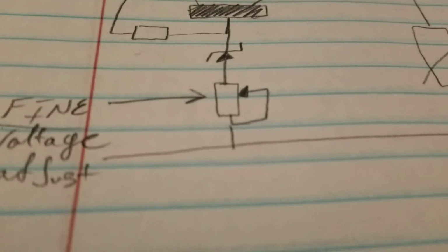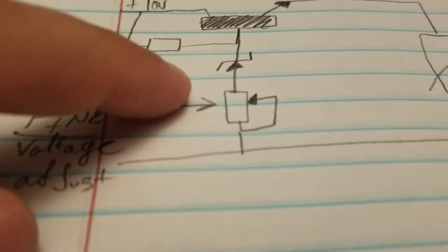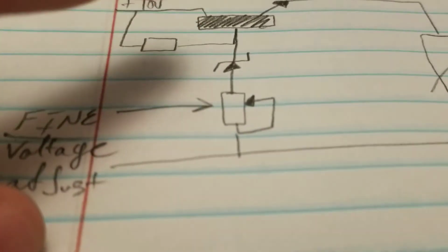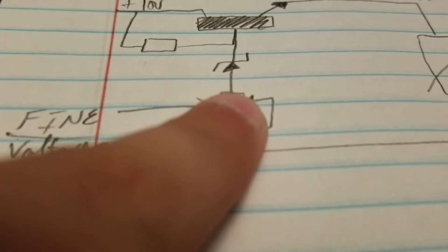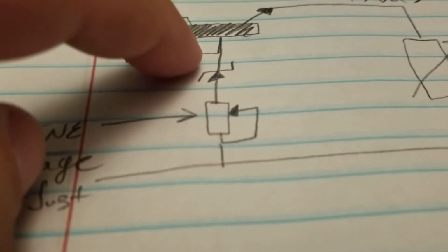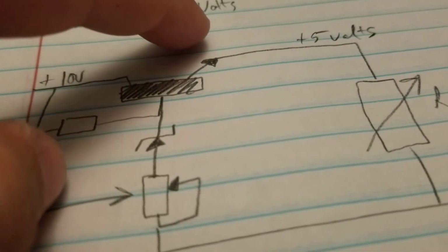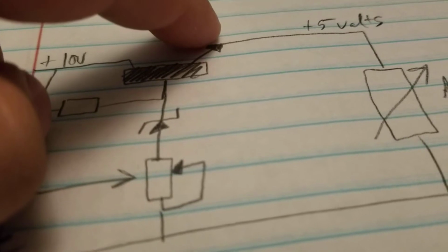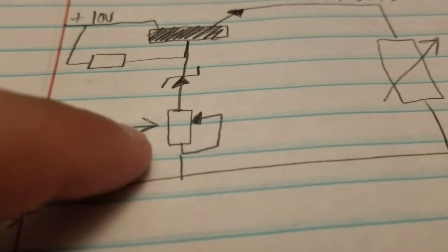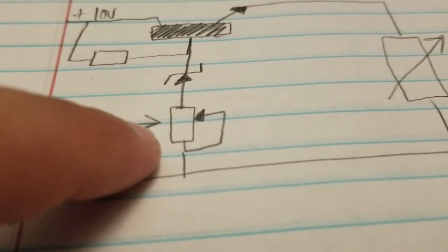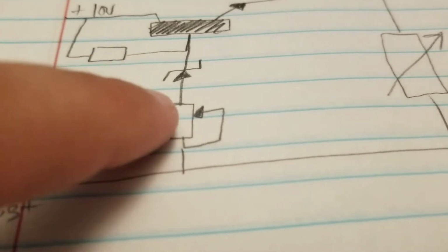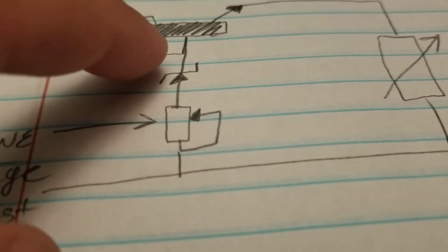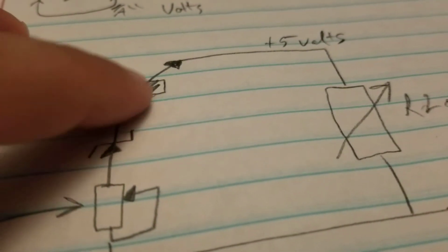And what you're doing is, say this is a 4.7 voltage drop Zener diode, right? If this resistor was nil, if this was connected straight to ground, that would mean this point's always going to be at 4.7, which means with the 0.7 drop, this is going to be at 4. So that's not good. However, if we have enough resistance here to turn this resistor up, so there's a 1 volt drop across here, the total sum between this node and ground would be 5.7 volts, which is about perfect for the 0.7 drop, giving us our 5 volts that are regulated.